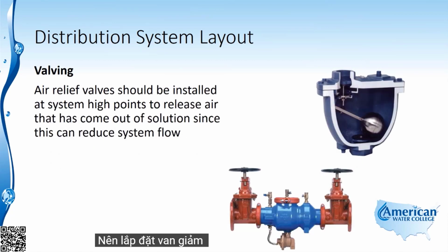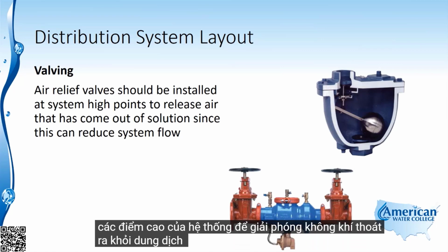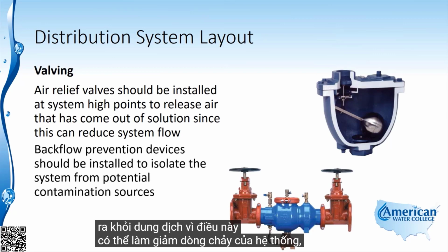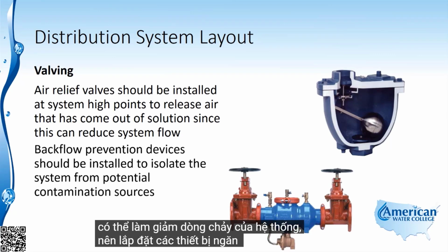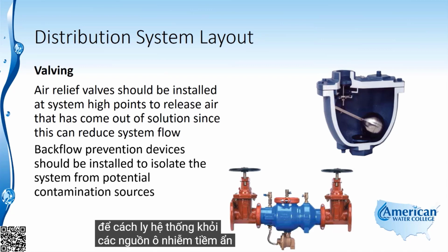Air relief valves should be installed at the system high points to release air that's come out of solution, since this can reduce system flow. Backflow prevention devices should be installed to isolate the system from potential contamination sources.